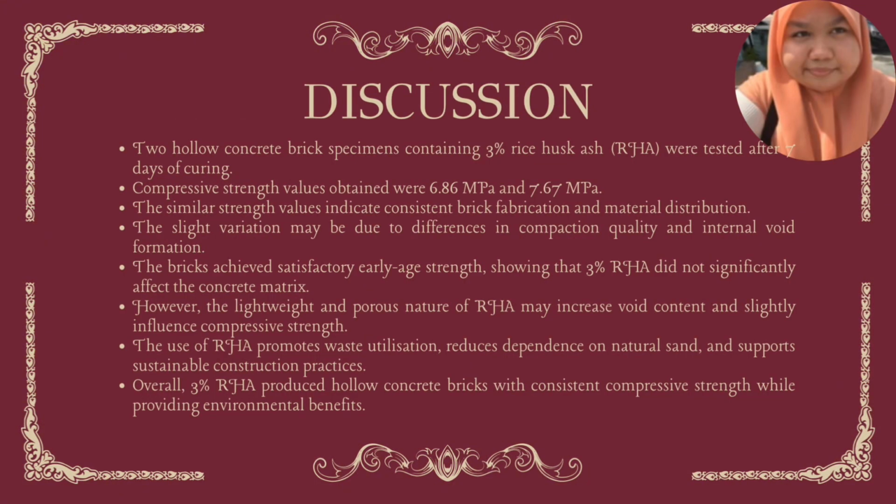2 hollow concrete brick specimens containing 3% rice husk ash were tested after 7 days of curing. The compressive strengths were 6.86 megapascals and 7.67 megapascals, showing consistent results. Overall, the brick still achieved satisfactory early age strength, indicating that the addition of 3% rice husk ash does not significantly affect concrete performance. From a sustainability point of view, rice husk ash helps reduce agricultural waste and decreases the use of natural sand, supporting more sustainable construction practice.